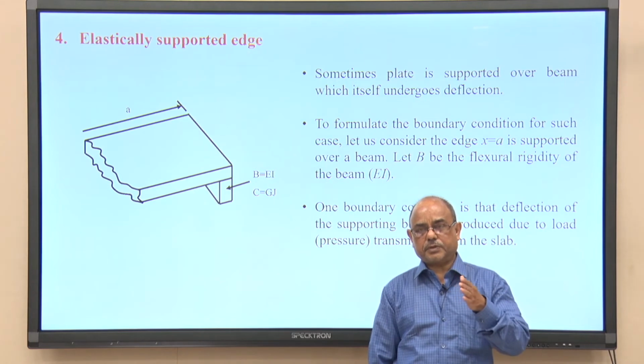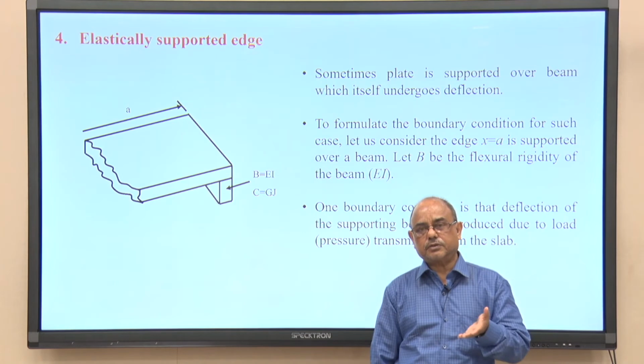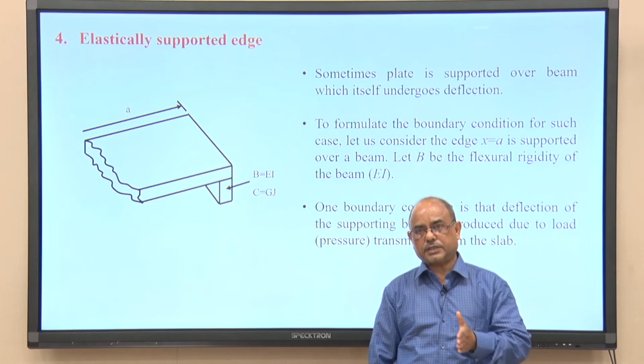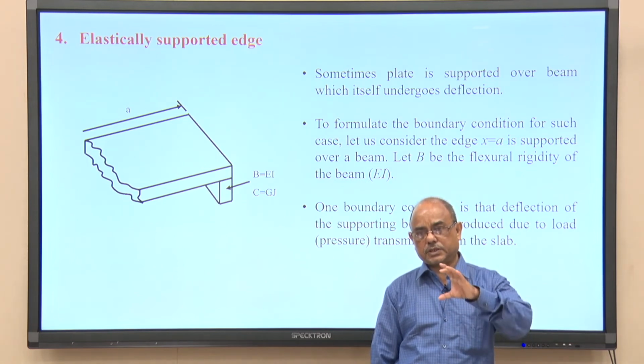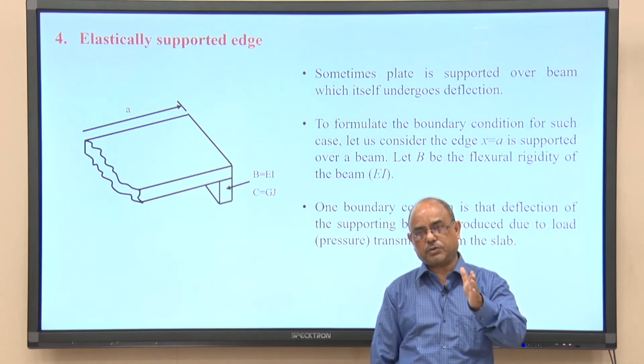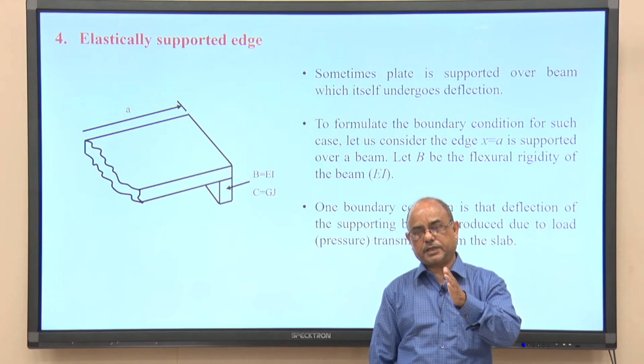So, coefficients are given and you can find from that coefficient. For a circular section, the torsional constant is very easy. For a circular section, J is nothing but the polar moment of inertia, but for a rectangular section or other thin wall section, the torsional constant is not readily determined as the sum of the moments of inertia, that is not equal to the polar moment of inertia.